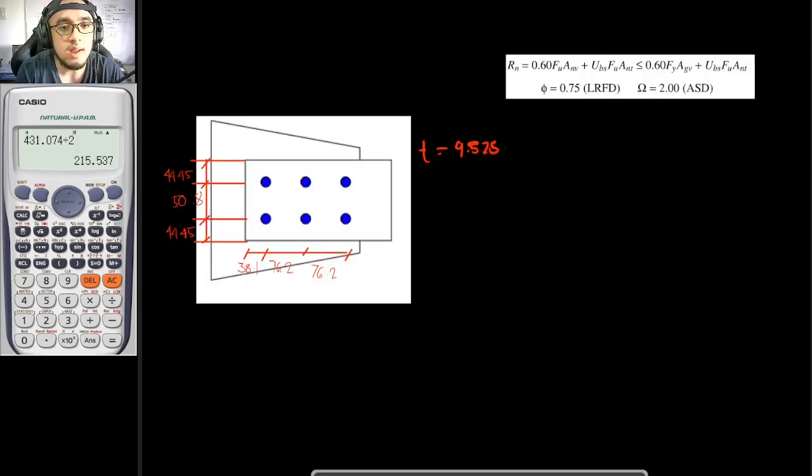So whatever you solve for this member would also be the strength of the gusset plate. If the properties of the gusset plate were different from the tensile plate, you should solve for their individual block shear strengths and choose the smaller value. That is if you are required to solve for the block shear strength of this connection.